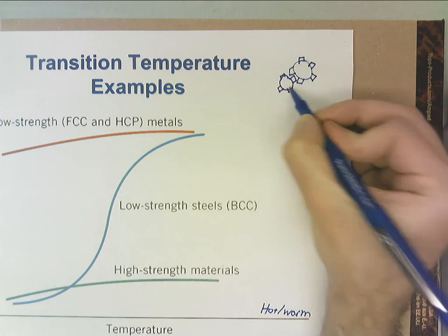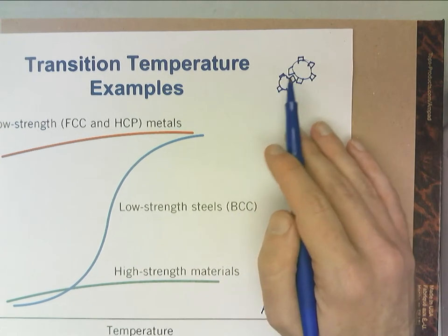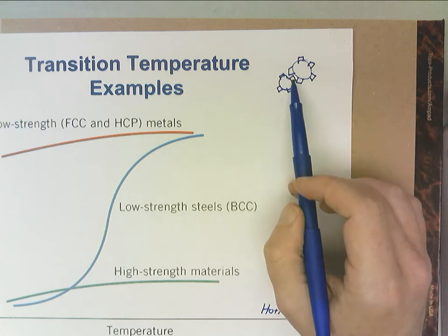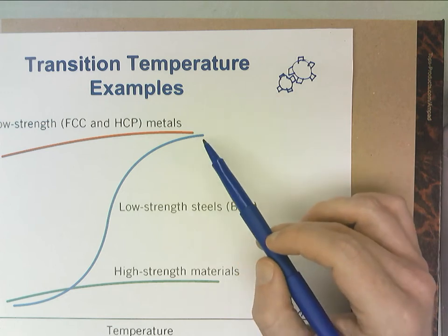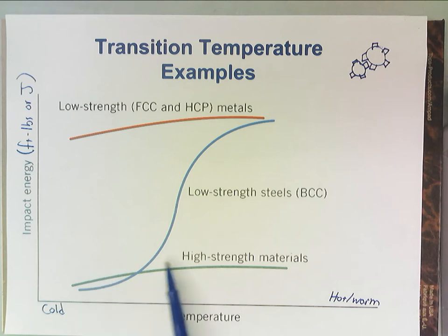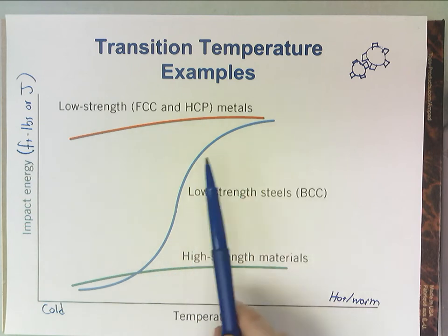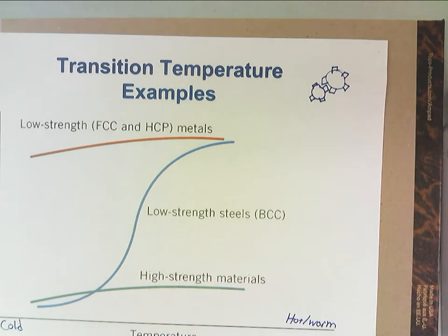The reason we don't want, say, a really high carbon content throughout the entire gear goes back to carburizing. We want a hard surface, but we want a soft inside. We're doing that for toughness because your really high carbon area is going to be something like this. Your low carbon area is going to be more like this or at least this. So as long as our gear is warm, it's got a high impact energy, high toughness.